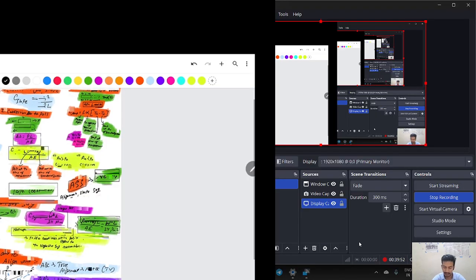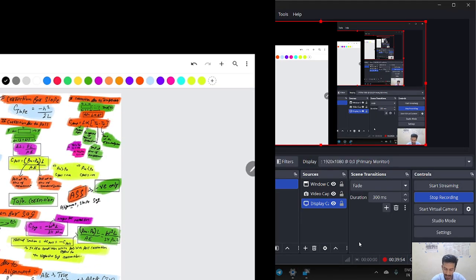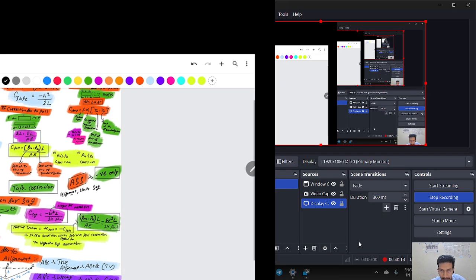They are not that much important, but remember, you know the correction for change in length and correction for change in temperature. This is new: correction for slope, hypotenuse square upon 2L.